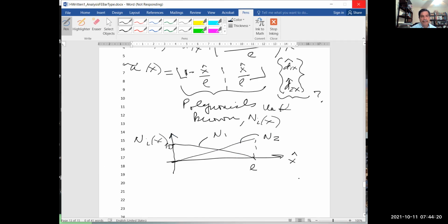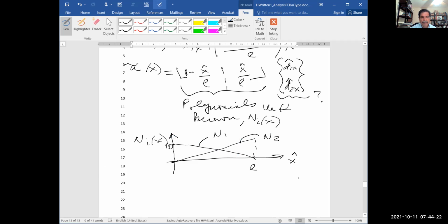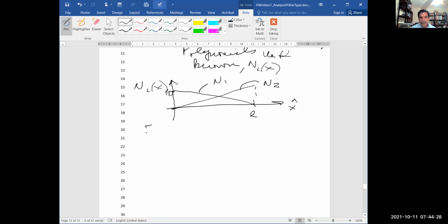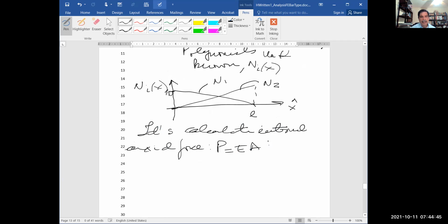Now, let's go on. After we have U, we can calculate the internal axial force. So we say that P is equal to EA du dx.